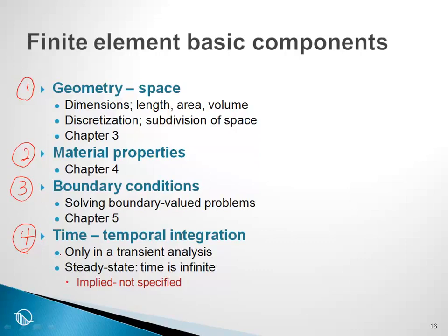Once again, this is fundamental to any finite element analysis, that you basically have 3 components for a steady state condition: geometry, material properties, and boundary conditions. And when we move on to transient analysis, we have one more item, and that is how are we going to step forward in time during the flow process.